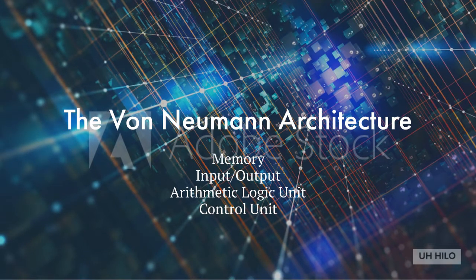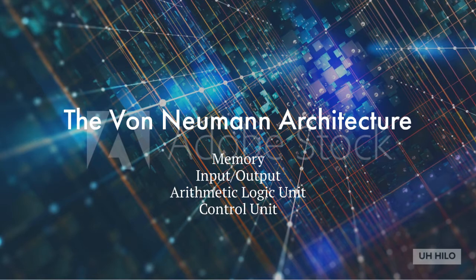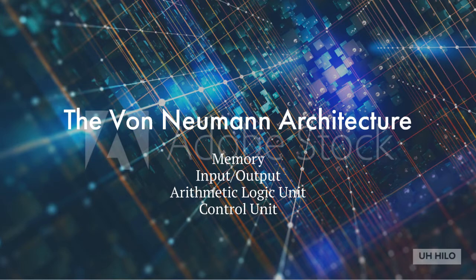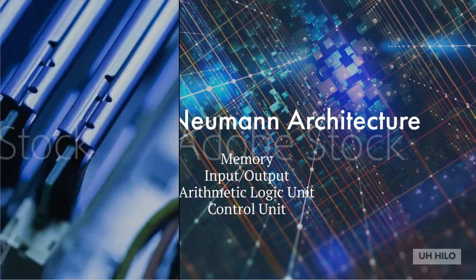There are four major components in the von Neumann architecture: memory, which is a functional unit where data is stored and retrieved; input and output, which connects the processor to the outside world; the arithmetic logic unit, which contains circuits for arithmetic, comparison, and logic; and the control unit, which fetches instructions from memory, decodes them, and executes them.